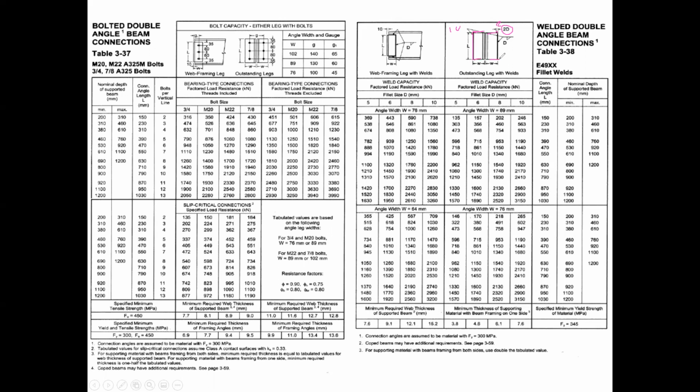You don't necessarily weld at the bottom here. The reason you do that is because you want the angles to be flexible and able to bend outwards so that you can get what we call a simply supported connection. Otherwise, your analysis would be off.